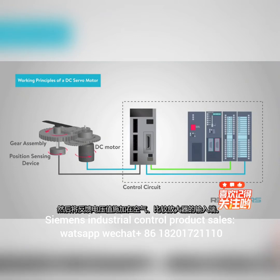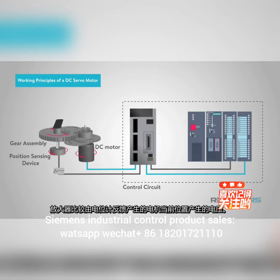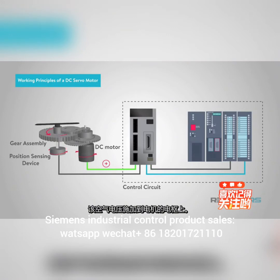Then, the feedback voltage value is applied at the input of error comparator amplifier. The amplifier compares the voltage generated from the current position of the motor, resulting from the potentiometer feedback, to the desired position of the motor, producing an error of either positive or negative voltage. This error voltage is applied to the armature of the motor.